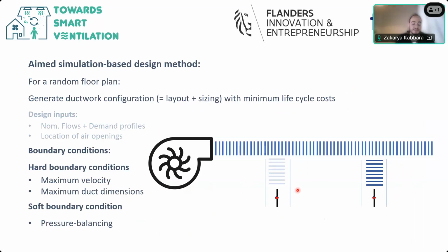Let's say this is the design that we have. It's unbalanced. If we rely on this design, then when commissioning or controlling this system, we will highly rely on pressure valves or dampers. The high reliance on pressure valves will pose some noise radiation from these valves and some acoustical issues. It may also have some control issues in the future as well.